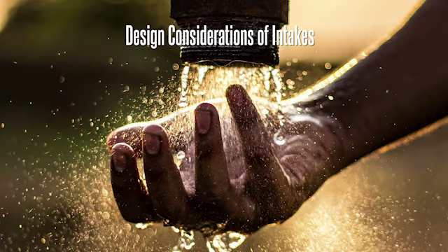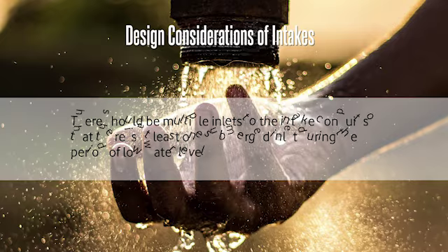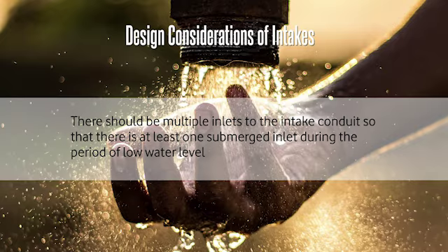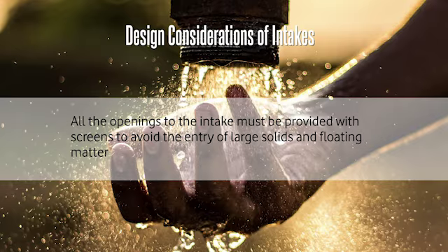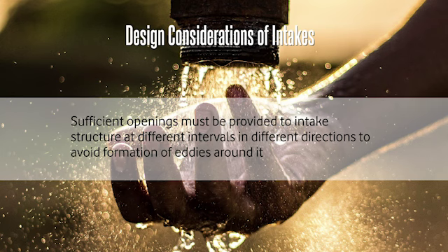Here, design considerations of the intake. There should be multiple inlets to the intake conduit so that there is at least one submerged inlet during the period of low water level. All the openings to the inlet must be provided with screens to avoid the entry of large solids and floating matter. Sufficient openings must be provided to the intake structure at different intervals in different directions to avoid formation of eddies around it.